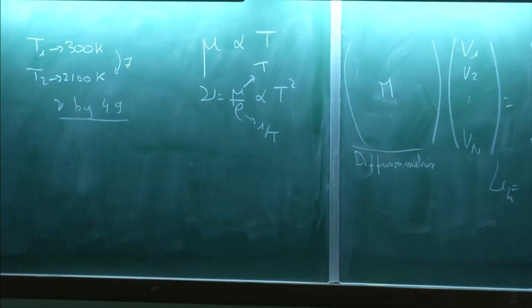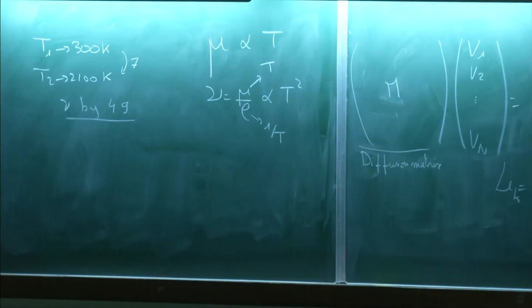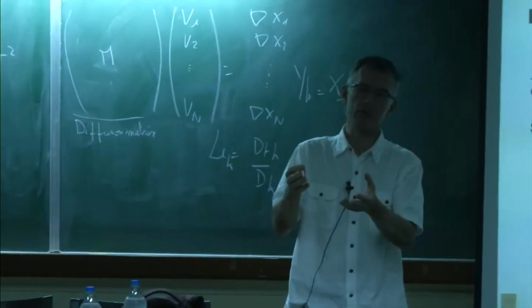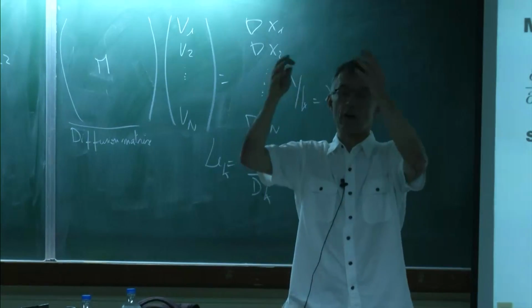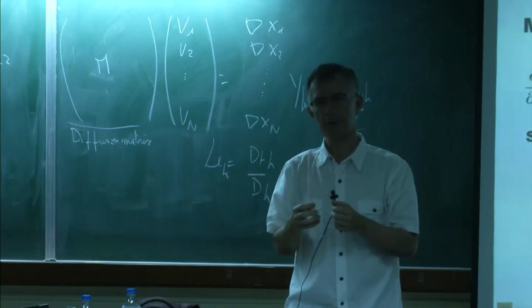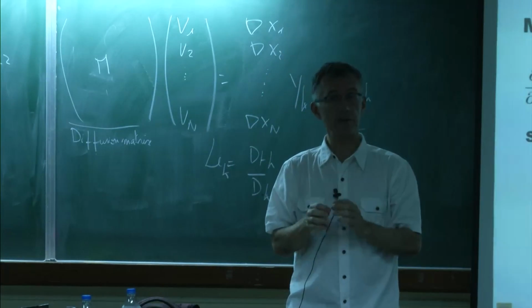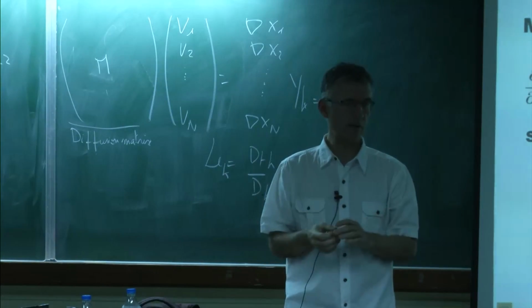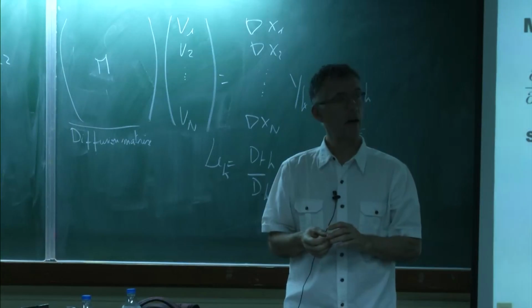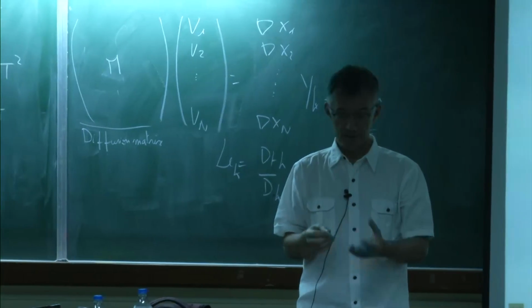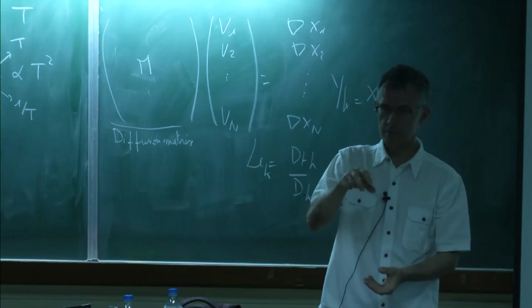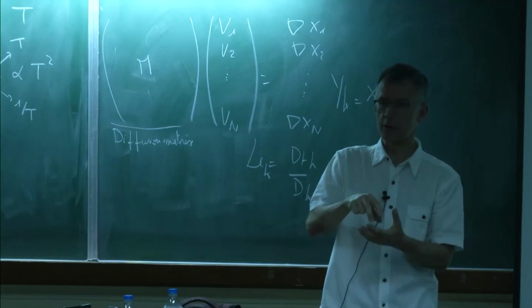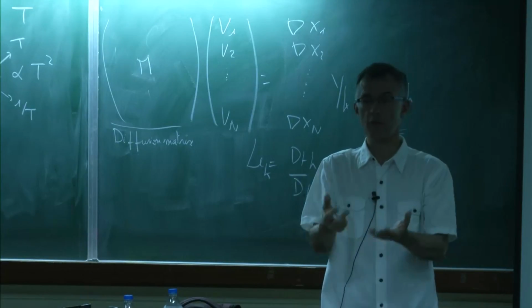Except you don't have this feeling, because when you look at a flame, your eyes are dominated by buoyancy effects. You see the burned gases going up because they are lighter than the fresh gases. That does not mean that they are not more viscous. They are actually more viscous. There are examples, I think in the book of Lewis and von Elbe, of a jet which is turbulent when it's cold, and when you ignite it, it becomes laminar because it's more viscous.